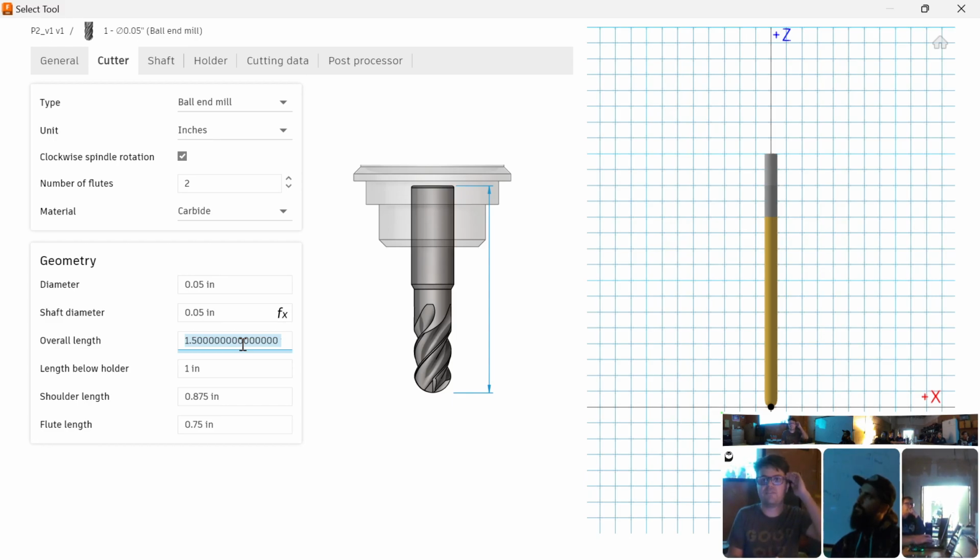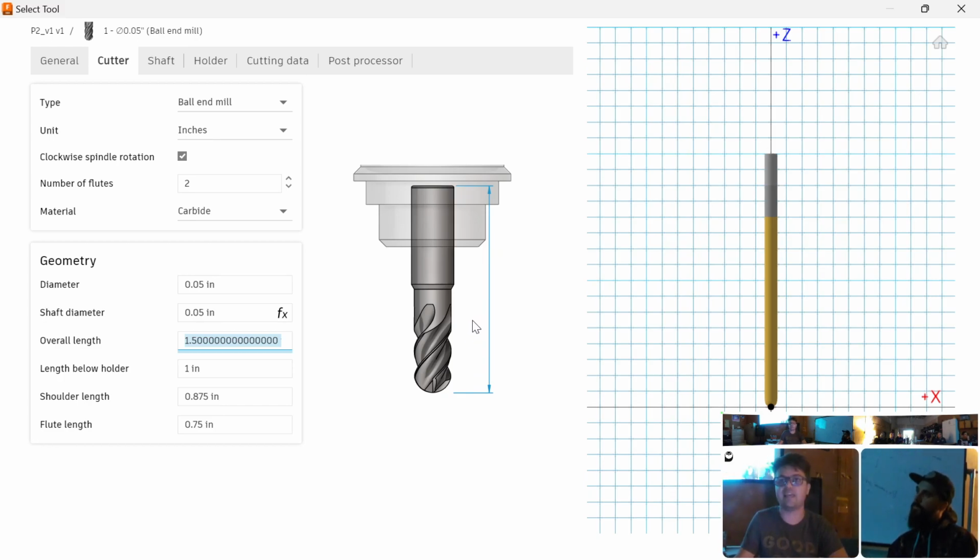You can ask Fusion 360 to do a lot of things for you. One of the things you can ask it to do is add the full tool holder here, and it will model the reach of the tool holder and figure out if the nose of the tool holder is going to hit part of your work as it's reaching into a deep pocket. Those are features that exist. You're not going to get taught them tonight. Google them when it comes up. But if you care to access those features, you need to set up the length of your tool correctly.